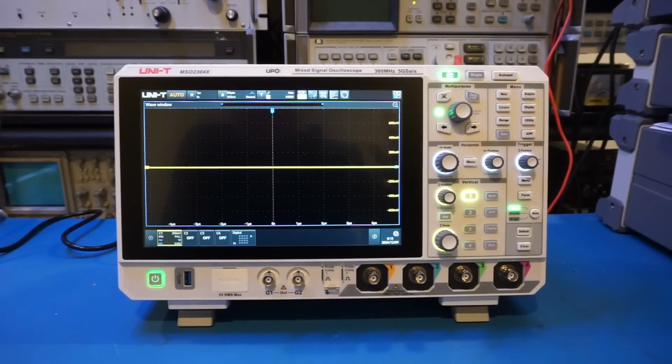Anyway, we can also independently verify the bandwidth of an oscilloscope using an Avalanche pulse generator, which can generate pulses with very sharp rising edge. The rise time is typically in the lower hundreds of picoseconds range, so by measuring the rising time of these Avalanche pulses, we can infer the front-end bandwidth. This method is capable of verifying the bandwidth of oscilloscopes well into the gigahertz range.